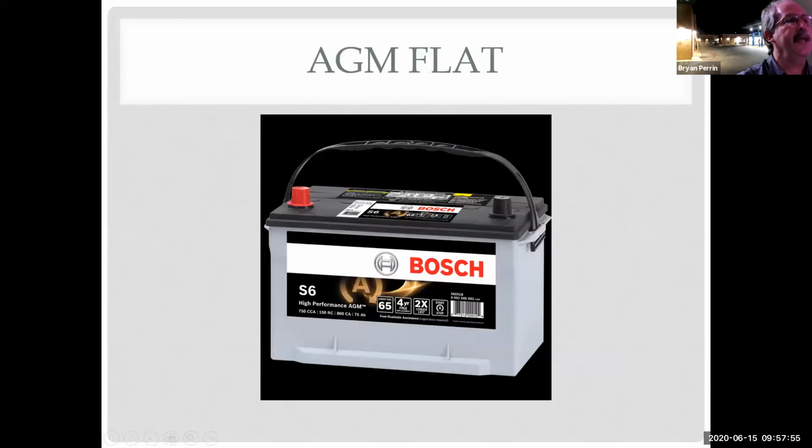This right here is an AGM flat battery. If you notice, it looks very similar to my other one. No serviceable vents on top. It's sealed. Now, just because a battery's sealed doesn't mean it's AGM, but this one does tell me it's an AGM battery. And these batteries do not like to be discharged below even 11 volts. These are very sensitive to voltage.